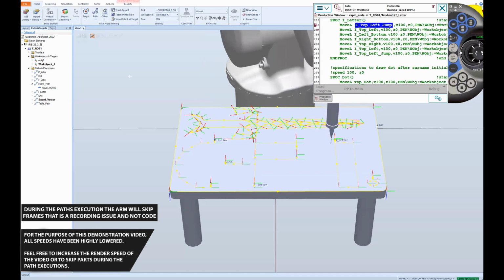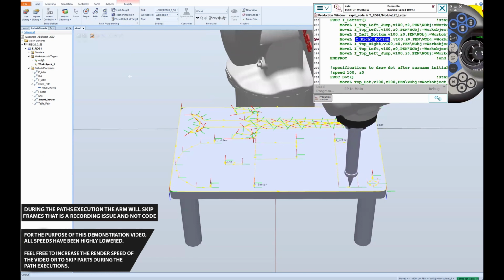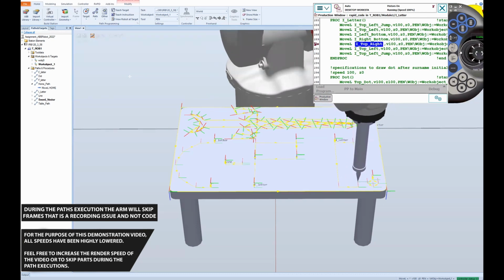While the robot arm is completing the last letter, it is important to talk about the speed refresh function, which is being used in order to take an input from the user, and depending on that input, give to the system either 20%, 40%, 60%, 80%, or 100% of the speed that has been set in the system. So if in the path itself, in the move-L function, for example, we've set V100, and then the user in the input chooses 20%, it will then become V20 instead of V100.